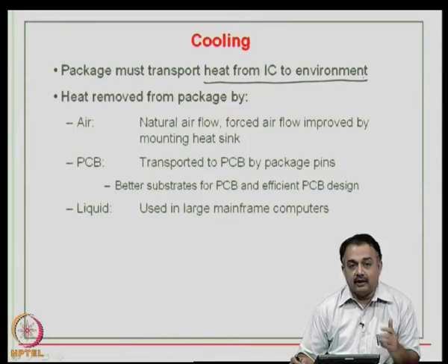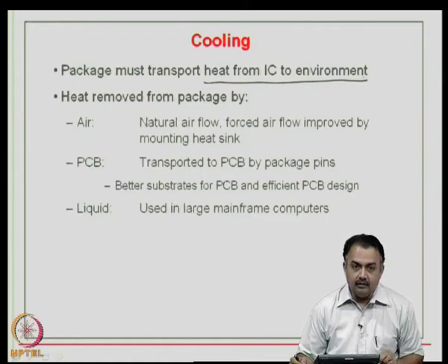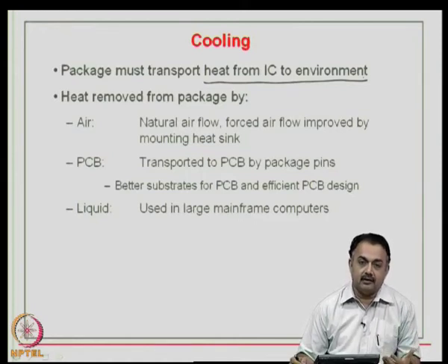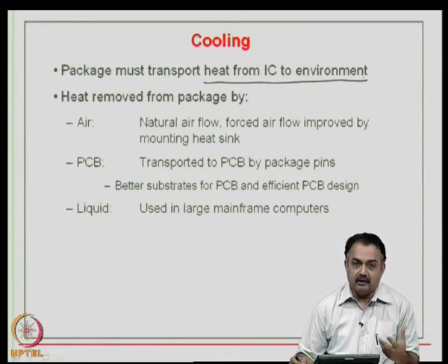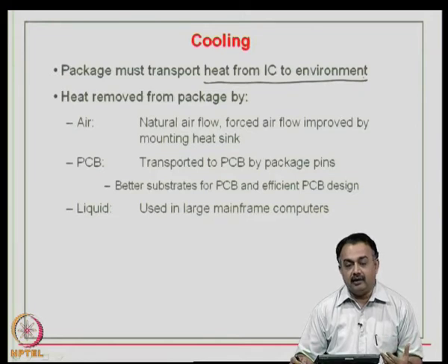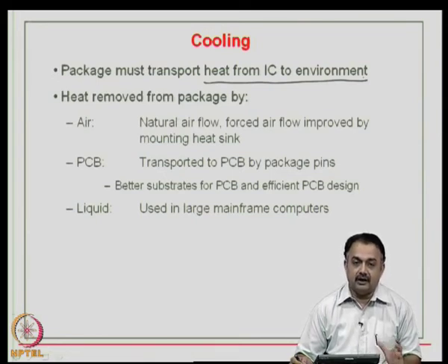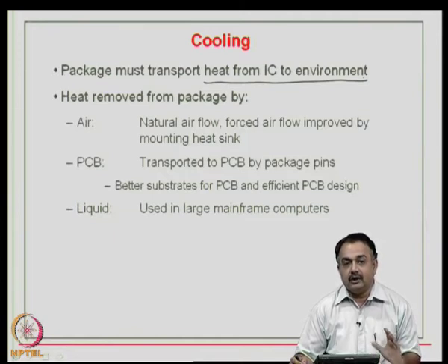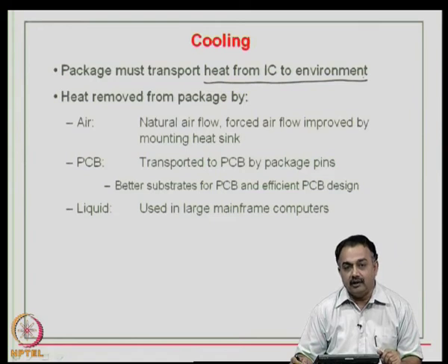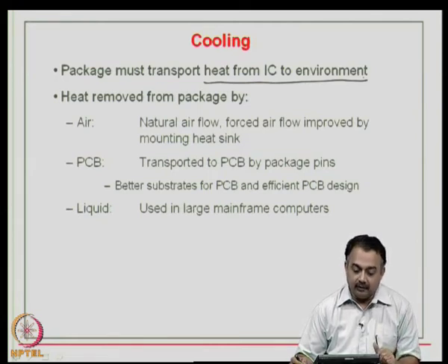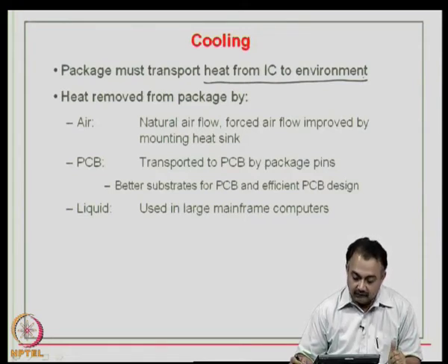Because if you look at the previous classes what we have discussed, when heat emanates from a die, when we power up a particular circuit, there is a silicon die, and if there is a heat buildup, there can be die crack because of heat accumulation, and there can be fatigue on the interconnect structures. So, it is a combination of silicon die, and then if you are using an organic substrate to place the silicon die, then there is going to be a problem in terms of warpage due to continuous thermal cycling at the organic substrate end also. Therefore, this heat has to be quickly removed effectively.